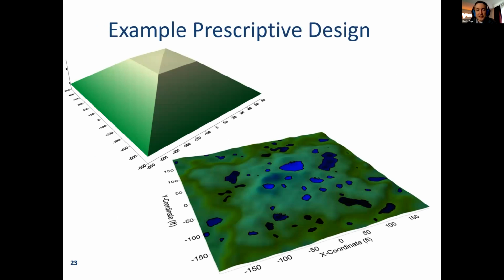I have on the screen a cartoon of a pyramid-shaped municipal solid waste landfill as it might be constructed using the current regulatory framework for landfill construction here in the US. If you grade that the way a lot of regulations are written, with the understanding that those regulations were written from the perspective of what has been tried in the past and deemed acceptable in terms of performance, and I focus on this flat part of the plateau on top, typically graded anywhere from 5 to 10%, what kind of pooling of liquid will I expect to see on the top? I have an example of what that might look like in a model here at the bottom.